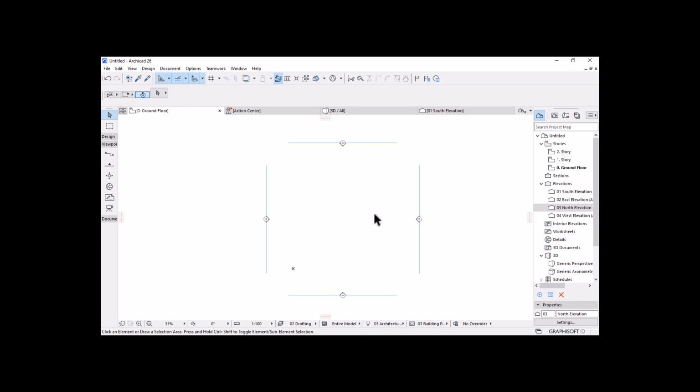We're going to use walls to place our layout. You could start by using 2D lines to draft or sketch your walls, but I will show you how to sketch using just your wall tool without wasting any time. So let's go here under design tool palettes and then activate our wall tool.